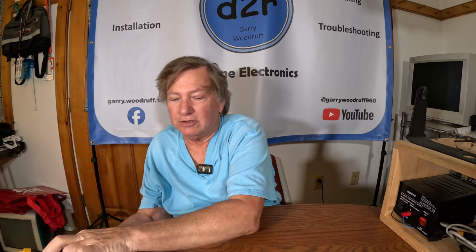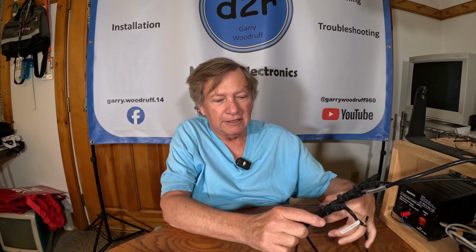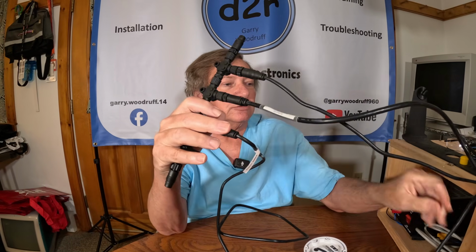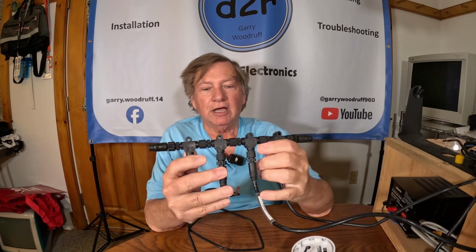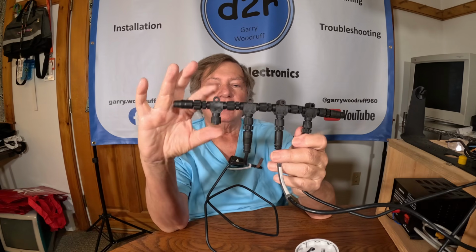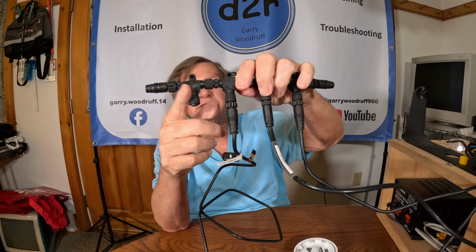It's straightforward. Now, the NMEA 2000 is a little different. It's what's called a balanced network, okay? And I've got a very, very simple NMEA 2000 right here. Let me slide this over so I get a little bit longer. Okay, this is a very simple NMEA 2000 bus, okay? I have these T nodes, okay? This is a NMEA T connector. All devices, including power, get connected off the bottom of this T.